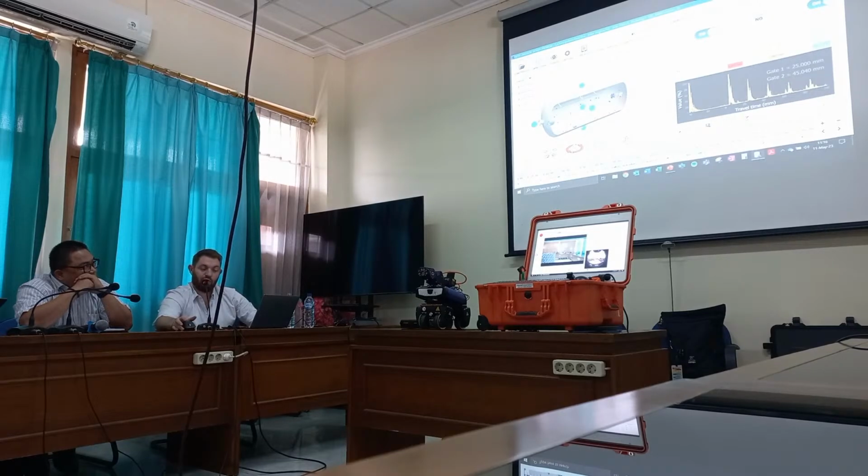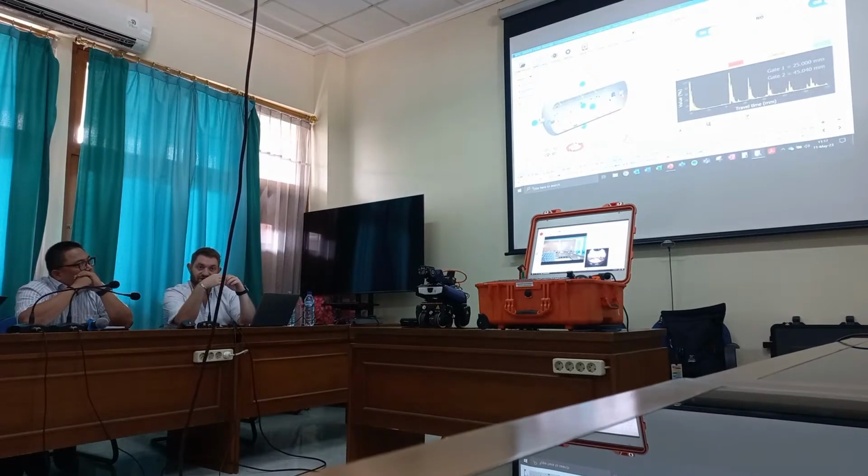Because what we're trying to be able to get to for our next step, in say 3 years' time, is put this robot back in through the same access point, push start, and it goes back and repeats that exact same inspection, the same locations, the same lighting level, the same zoom levels, to give us that repeatable and comparative inspection, which starts to lead us into the automated inspection, being able to pre-plan that in that simulator, so that whatever we drive around that simulator, it does the same thing. We then take that mission and push start, and the robot goes and does the inspection as we've programmed it to do.